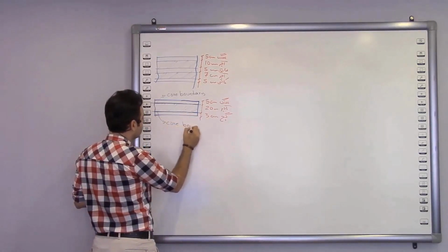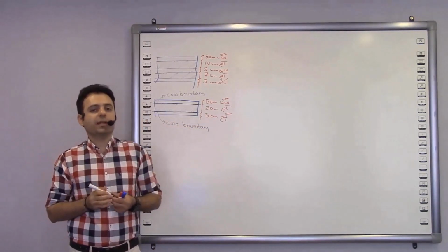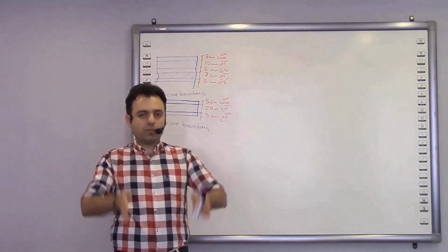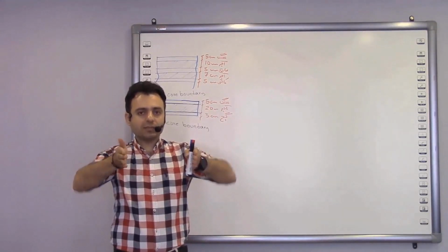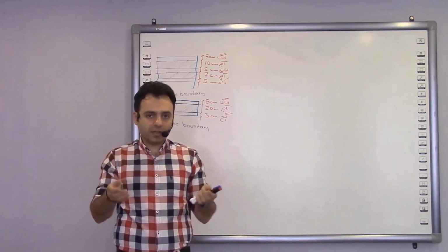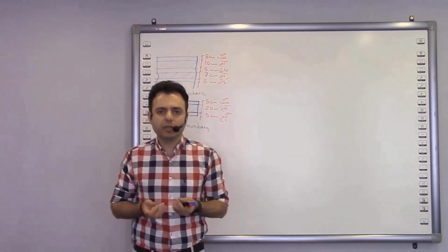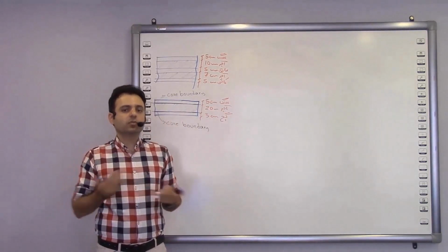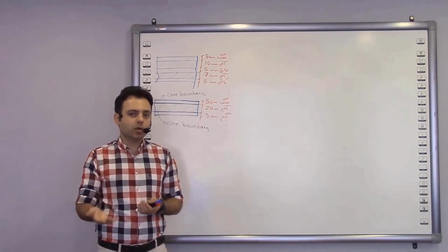Core boundary. Now, what are these two core boundaries? Let's talk about them a little more. Imagine a wall that its structure is now completed. Alright, now those two surfaces on the structure are called core boundaries, and the finishes are out of that. Actually, the surface of our structure is called core boundary. Now, what is the function? Core boundary separates the finish from the structure. You see, this is its main job, separate the finish from the structure.